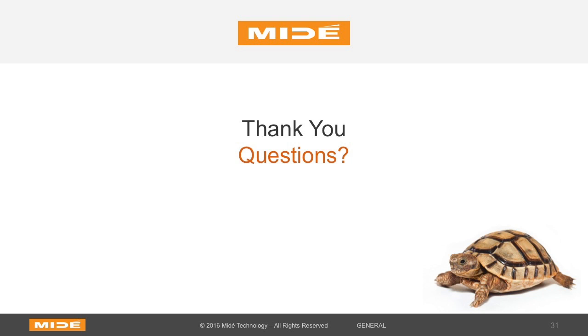The thing I haven't really touched on in this webinar, and which we talk about in more depth in that ebook, is simulating some shock and vibration in the lab with a shaker system. That might be something you'd have to do if you're developing an isolator or damper. Shaker systems can run $30,000 or more, so you might have to go to an outside testing facility like NTS to do the testing for you once you've developed the product. But I would use a PSD and the shock and vibration response spectrums before and after, or with and without your isolator, as a way to present the effectiveness of your product.